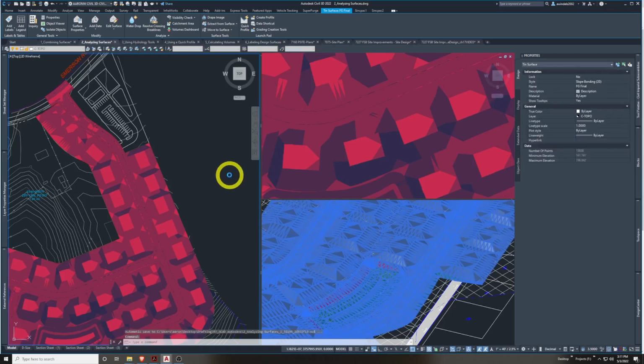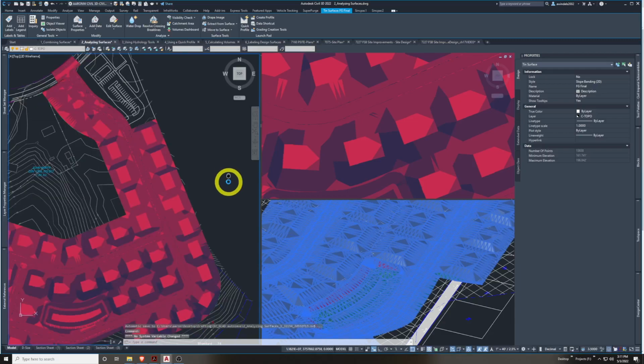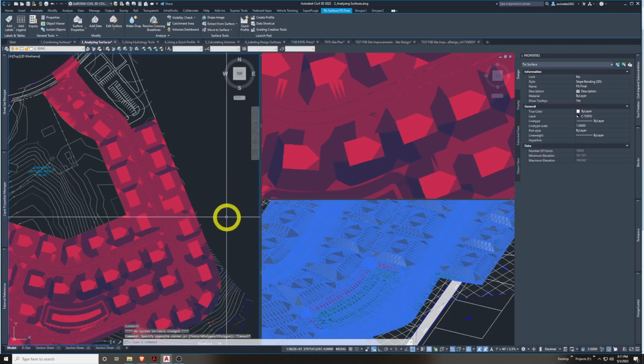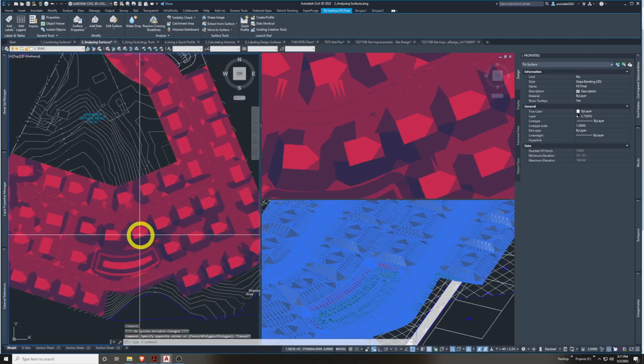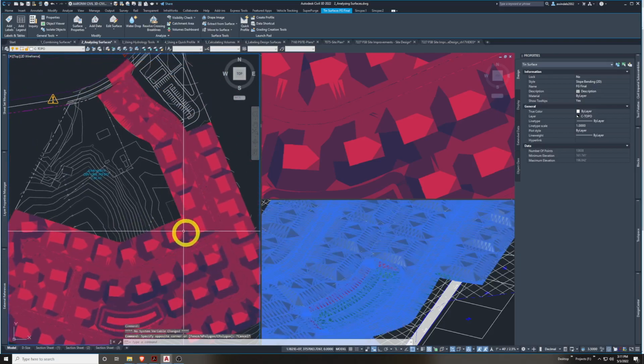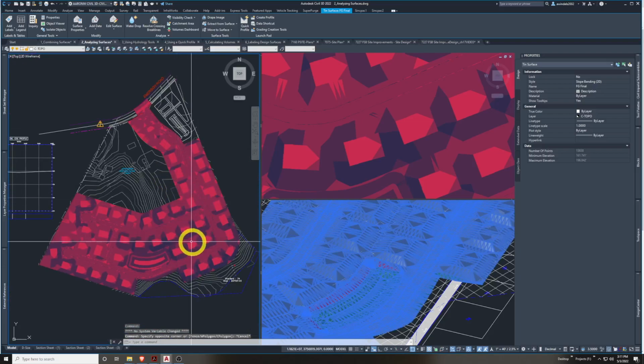So this really shows where my big slopes are, and where my flat spots are. My darkest color is where I have my most aggressive slopes. I wouldn't build there. Or maybe that's because I built a pond there or various other things. You're just getting an idea of the most buildable areas of a land development site in this case.